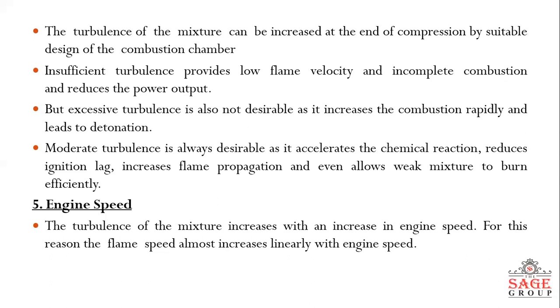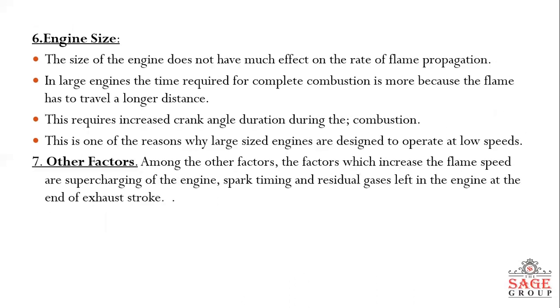Next is engine speed. The flame speed increases almost linearly with engine speed, since the increase in engine speed increases the amount of turbulence inside the cylinder. So the time required for the flame to traverse the combustion space would be halved if the engine speed is doubled.